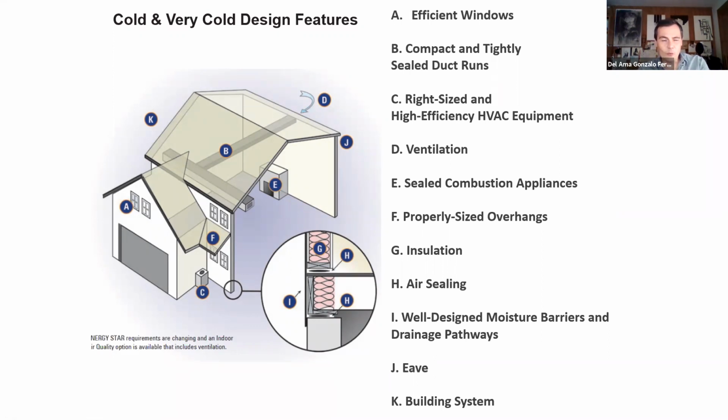We need to expose those windows to the sunlight in winter, but in summer we have to cast shadow on that window. That's a question about geometry. We need to know the sun path in the sky, and it's very easy to know that. Then we need to control the height of the window and the length of overhangs or eaves. What is an overhang?